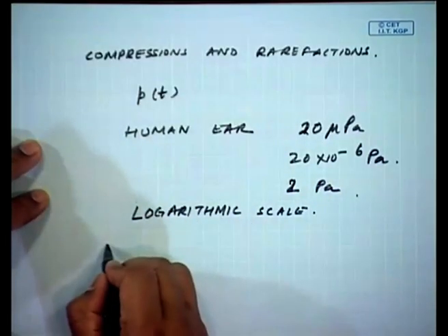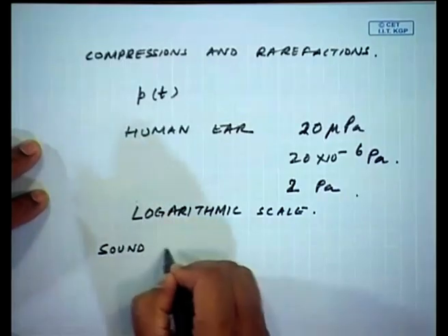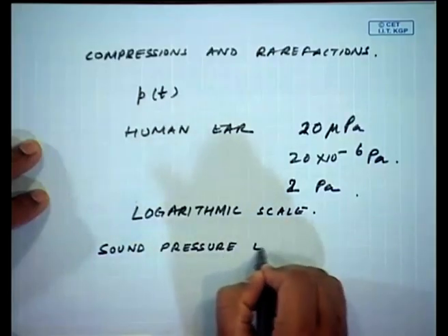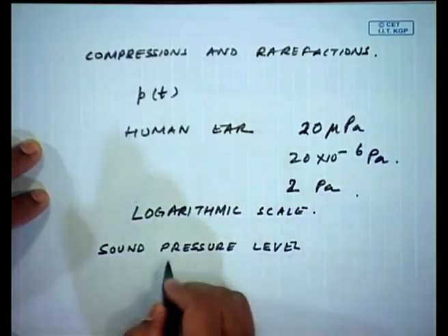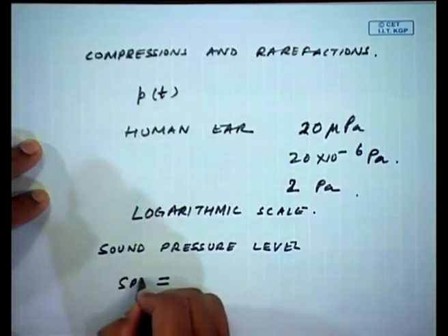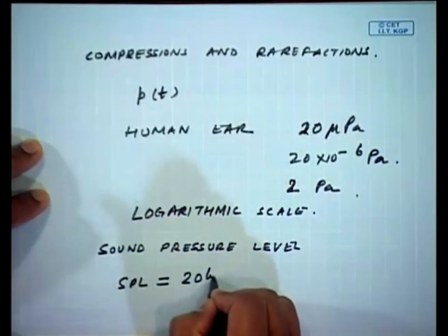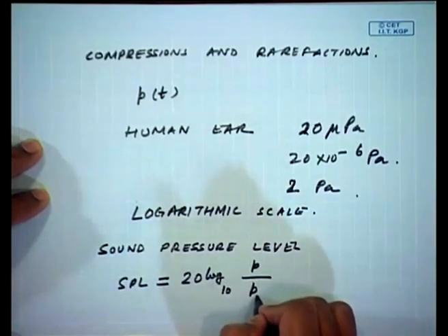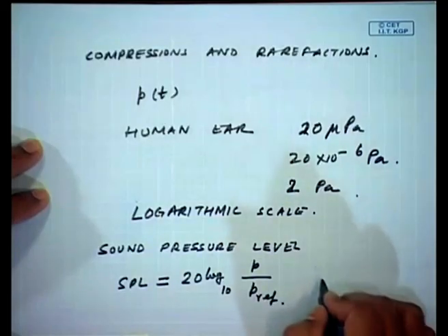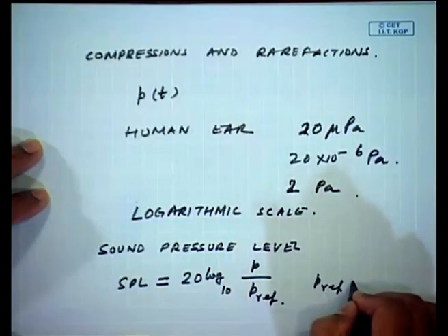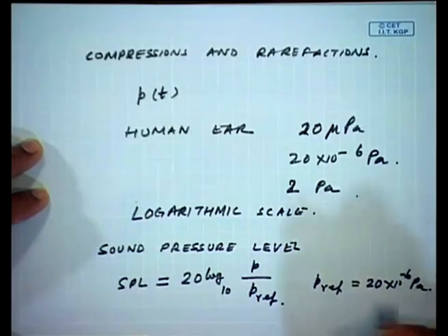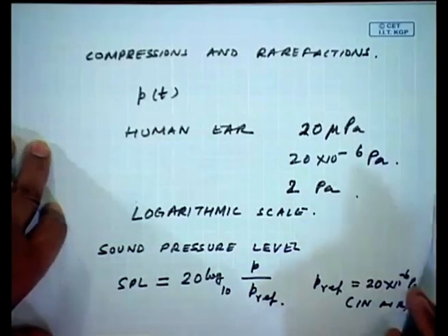wherein we define something known as sound pressure level, as SPL, as 20 log to the base 10 of p by P reference, where P reference in air is 20 into 10 to the power minus 6 Pascal in air. In water it has a different value.